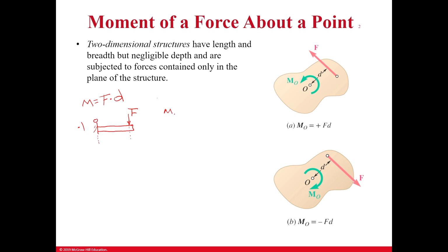So moment at O is distance L times a force F. Notice that this is rotating clockwise, therefore this is going to be a negative moment.